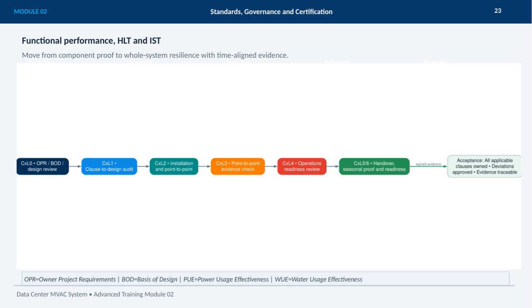Moving into integrated scenarios, we then apply a representative load and reconcile this with the measured duty, holding the system until it stabilizes to capture accurate data and record uncertainty. Restoration proof involves initiating controlled failures and verifying responses from both automated systems and operators, checking remaining capacity and temperature excursions carefully. To complete the process, we return the system to normal operation step by step, confirming standby availability, addressing all overrides and alarms, and signing off on restoration.